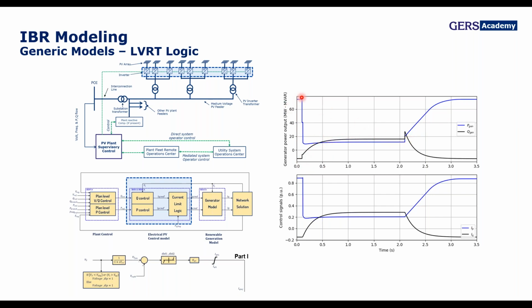When the voltage goes down, the inverter reduces the active power, but as you see here, the response from the reactive power just follows a proportional control. You have a dead band, and after that you get a response of that branch. As soon as you recover or clear the fault, you go back and follow the rest of the control.